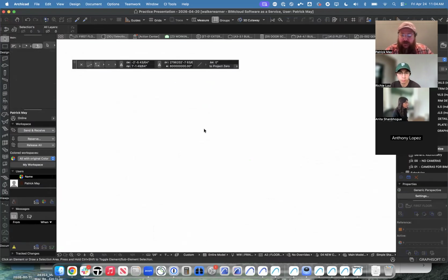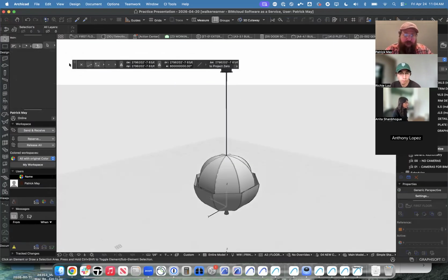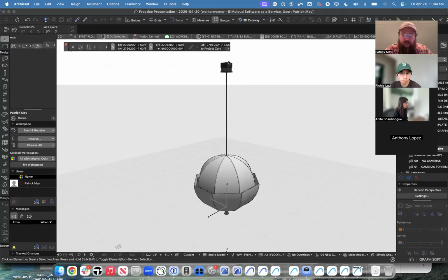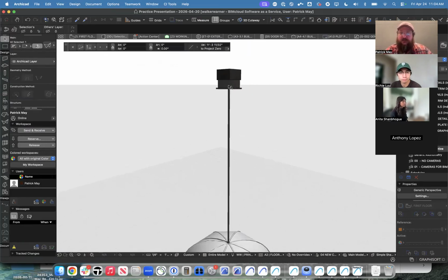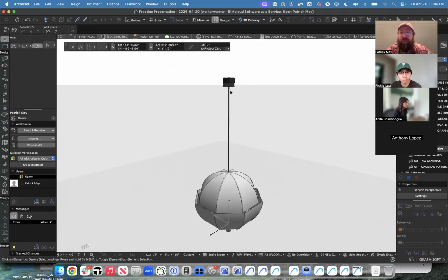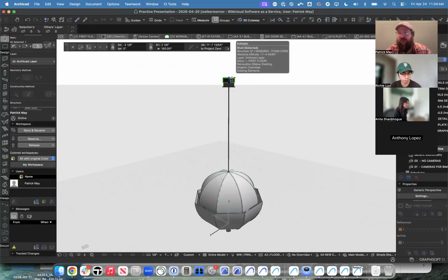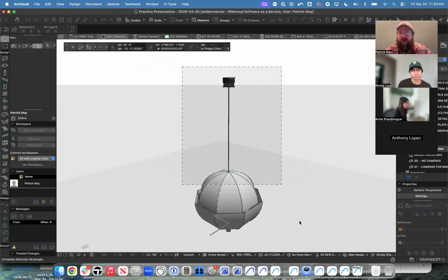The other thing that we have on that object is, let me go back into this and look at it, I've added a box, the junction box. We can create parameters to turn these things on and off really easily. So that's what I want to walk through: how do we make this hang height adjustable, make the lamp resizable, and make this box something that we can turn on and off. Okay, that's our goal with this one.